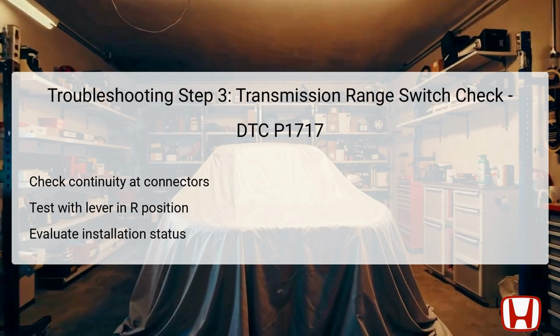You'll need to check for continuity between test point 1, which is terminal number 1 of the connector, and test point 2, terminal number 10. It is essential to keep the shift lever in the reverse position while checking for continuity. A successful test will present continuity in this position, while shifting to other positions should show no continuity, confirming that the switch operates as intended.